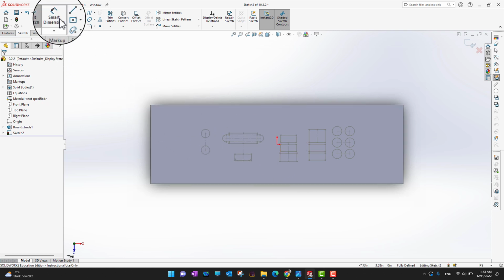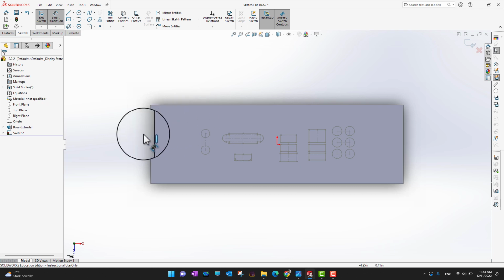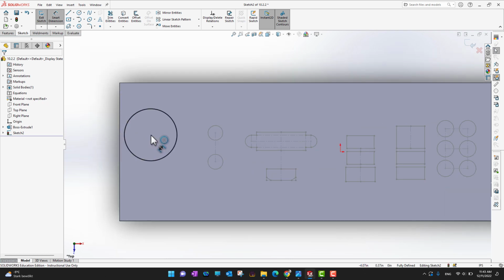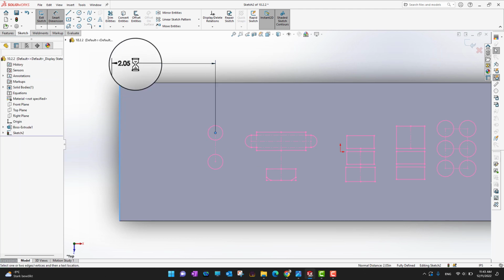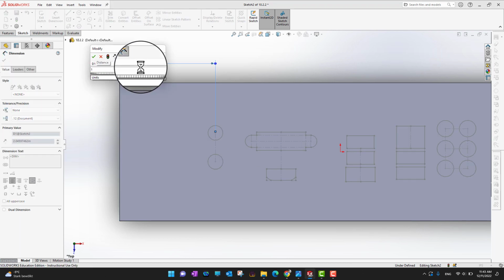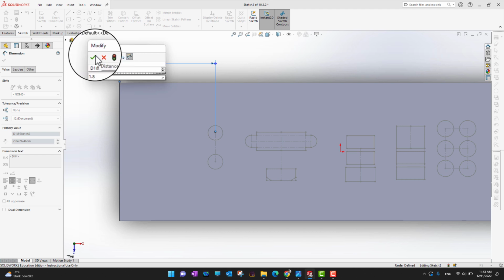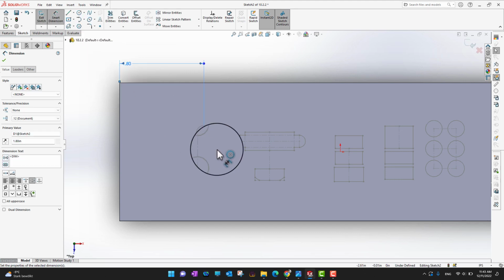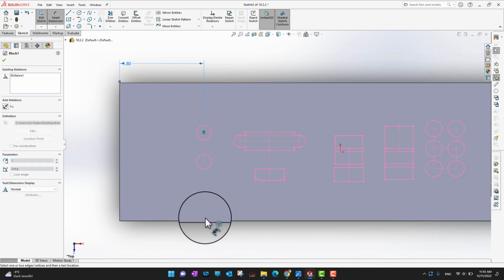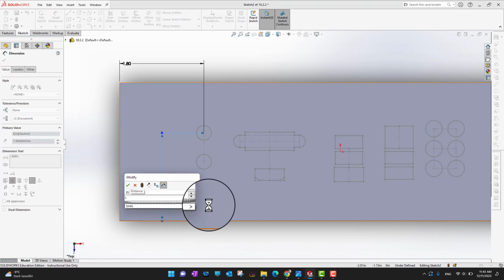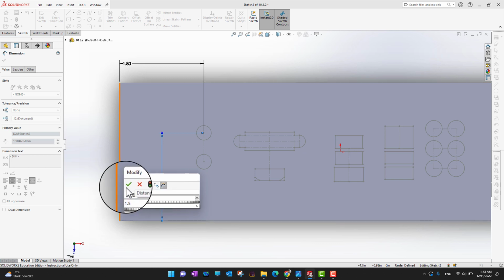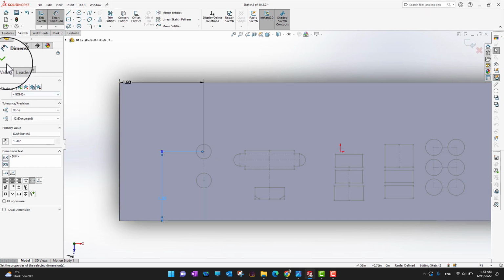So what I can do is, there is another thing, I would like to have some dimensions. If I want some dimensions, like a specific distance I want to create from the side, I can select 1.8. And if you want to set the height as well, I want to insert it at a certain height. I would say I want to insert it at 1.5 inches high like that. And when you are done, you can just click the green check mark.